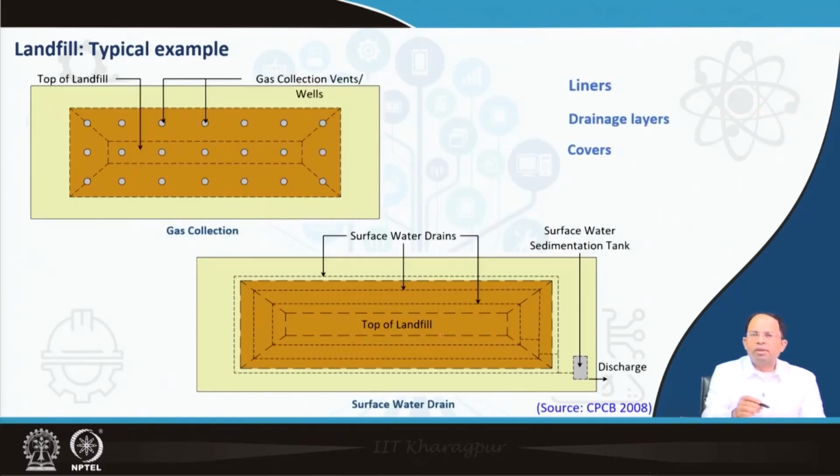Now once the landfill profile is designed, then we can determine the placement of the gas collection wells. So this has to be predetermined. We can design not only the gas collection system but also the drainage system and so on. Those layouts could be designed earlier based on the profile of the site as well as the section and so on. At the top of the landfill, we can design the surface water drains, at what height we will design the drains. So this needs to be predetermined. The liners, drainage layers, covers, all can be predetermined when we design the entire landfill, and before actual operation all these designs need to be finalized.